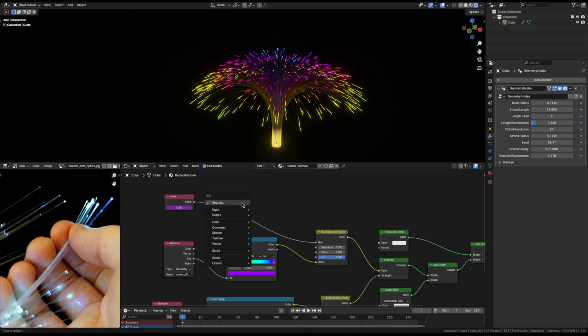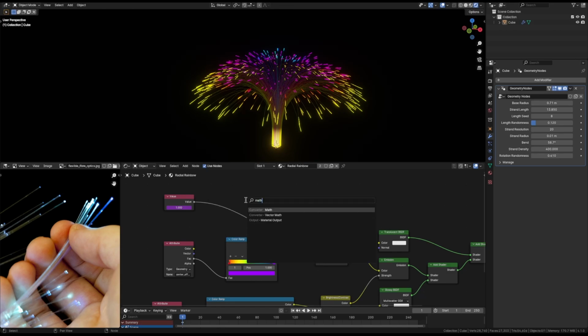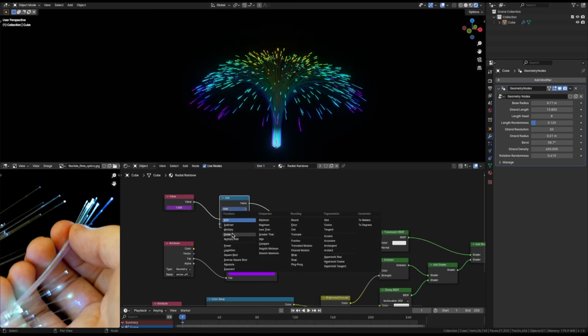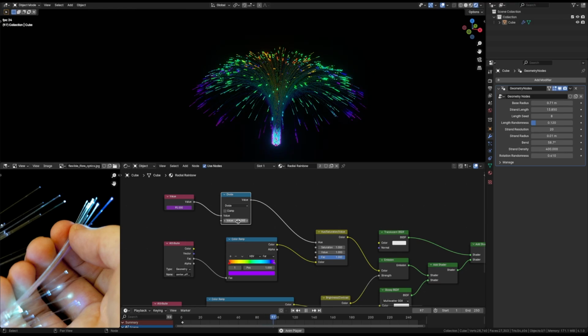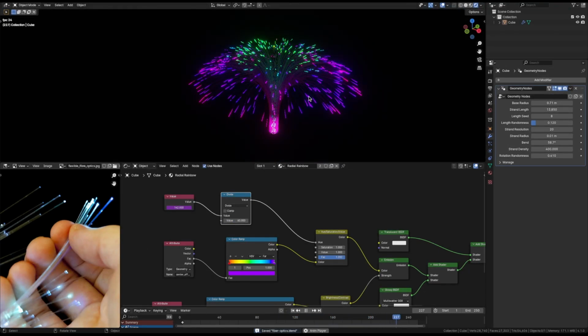Right now it's going to be super fast, if it works at all, because we want the hue value to be between 0 and 1, so let's add some math here to divide this by some number, let's say 180 for now. And you can use Shift Left Arrow and Shift Right Arrow to move between the start and the end frames, if you look at the bottom. So Shift Left Arrow, press spacebar to play, and you can see how the colors change. That might be a bit too slow, so we can speed that up.